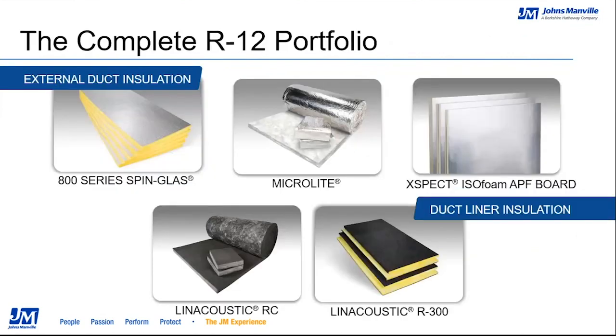So with that, due to energy codes constantly changing, we at Johns Manville have a complete R-12 portfolio. The 800 series Spin-Glas board we discussed meets an R-12 at 3 inches thick. The Microlite duct wrap that we just discussed meets an R-12 at 4.4 inches thick. The LINACOUSTIC RC liner meets R-12 at 3 inches thick, and the LINACOUSTIC R300 liner board meets an R13 at 3 inches thick. Lastly, in the top right there's an X-Spec ISO foam board. This product meets an R12 at 2 inches thick, which is pretty significant.